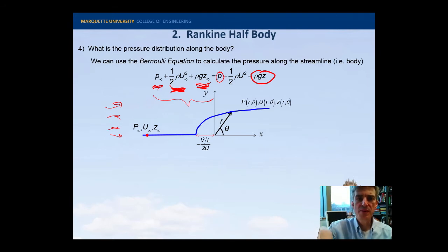And the sum of these three is equal to the change in the pressure, in this case along this body, plus the dynamic pressure, which would also be a function of the shape of the body, and then the change in hydrostatic pressure. So these three are equal to those three. And you remember how this goes from your undergraduate fluid mechanics. We typically neglect this hydrostatic pressure, and then we see that we have this inverse relationship with pressure. As the pressure goes up, the velocity's got to go down, or vice versa. The velocity goes up, the pressure goes down.